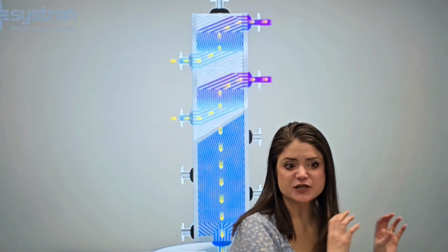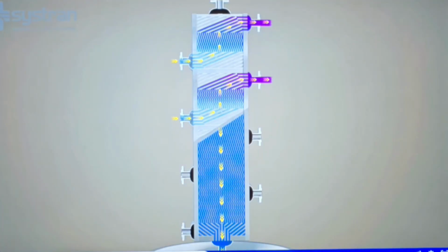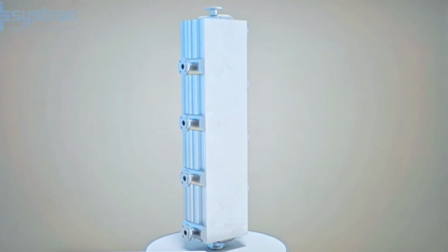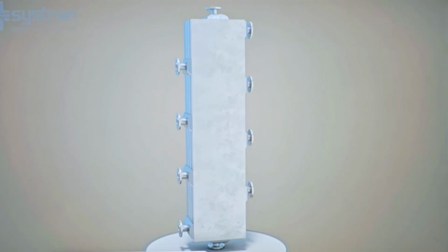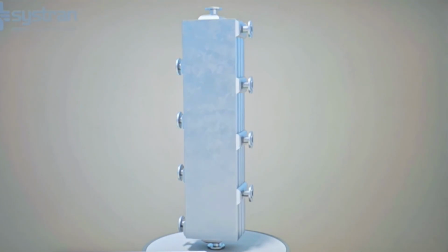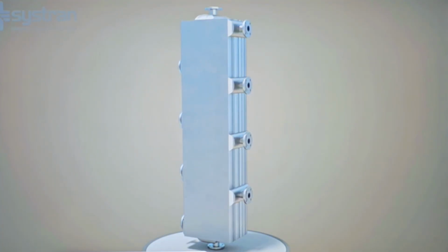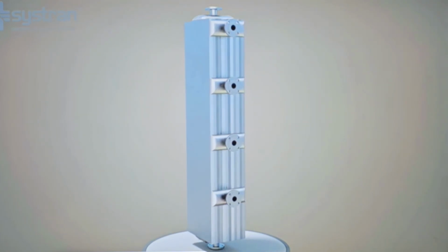So the inlets and outlets, where they're coming from and where they're going, that's going to be process specific to a specific plant and a specific unit. That's not necessarily where it's going to be coming from or going at a unit you end up at. Refrigeration system for compression or cooling before returning to the exchanger. Depending on the configuration, several flows can run through the heat exchanger concurrently to increase heat transfer efficiency and further cool the feed. The number of layers, type of fins, and stacking arrangements can vary depending on the specific design and application of the exchanger.